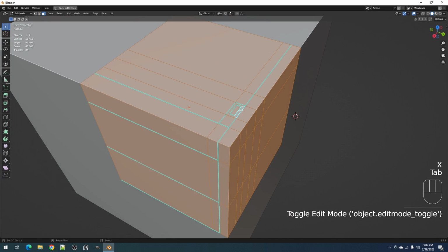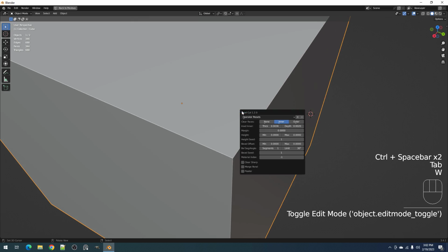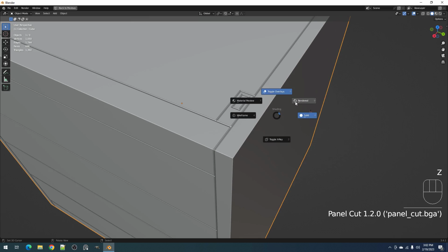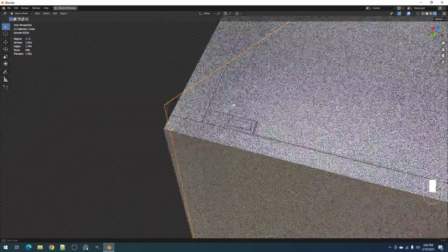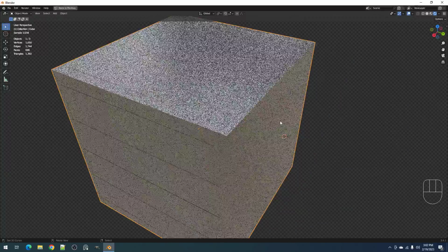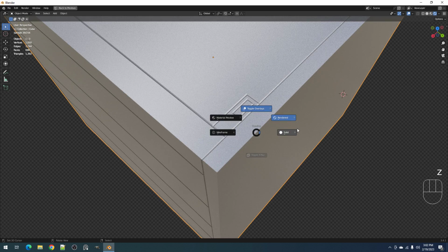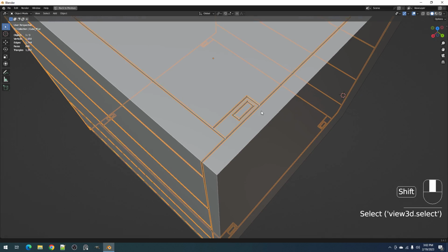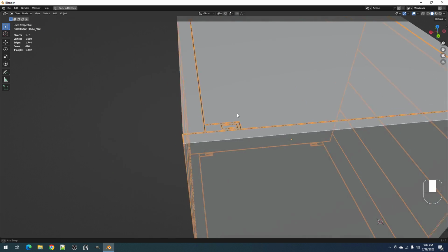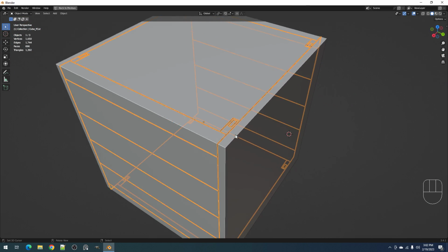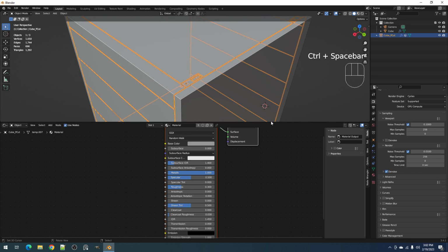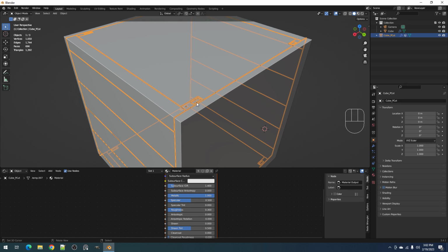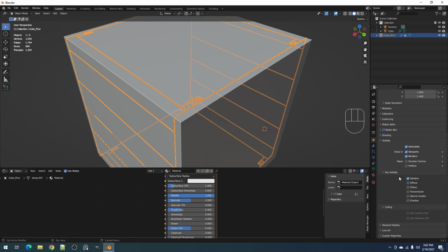So if we toggle on floater, now it looks like the resulting panel object is part of the source object underneath, because it turned off the ray visibility in the object properties for the panel cut object, for the diffuse, glossy, and all the rest, except for the camera.